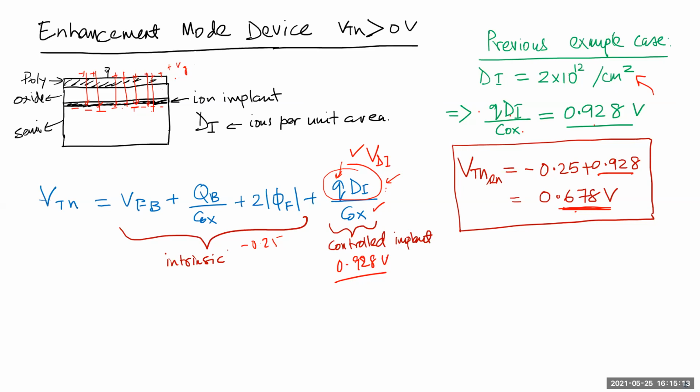So they'll grow a thin SiO2, put photoresist on it, mask it, take the SiO2 off, then do the ion diffusion, because the diffusion will diffuse into the silicon, but not into silicon dioxide. It'll contaminate a little bit, but then you dissolve all the SiO2 off and then do the processing again.